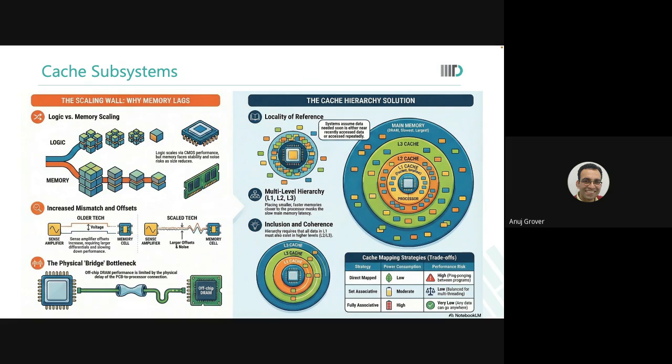As a consequence, my miss rate reduces. It's a neat compromise between a direct map, which is definitely very low power, no comparison needed, just look at the LSBs and send it ahead, or fully associative, a lot of power because my data could be anywhere and I have to compare every tag. Set associative means only the number of ways that I have, only that many tags I need to compare. That I can do in parallel.